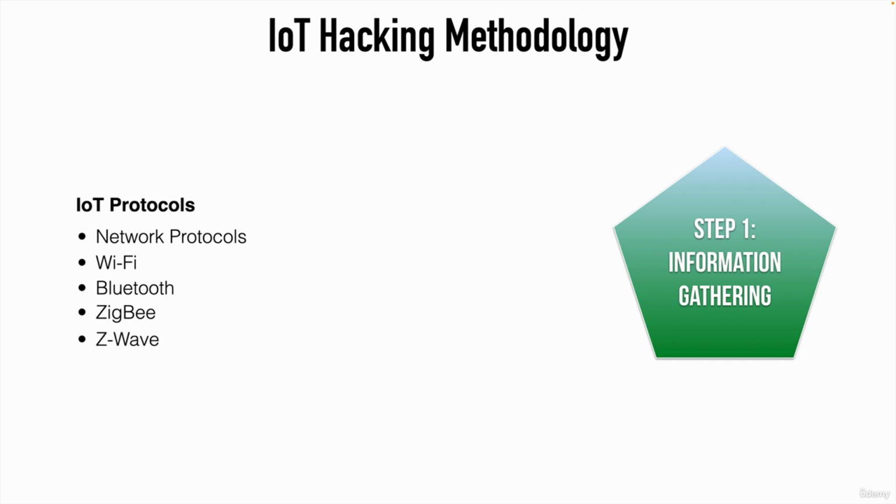This is also a low-power alternative to Wi-Fi, and it has a much larger range than Bluetooth. Z-Wave operates in a different wireless frequency as opposed to the previously mentioned Zigbee. So where Zigbee has to deal with potential congestion on the 2.4 gigahertz band, Z-Wave operates in the less crowded 800 to 900 megahertz range. For that reason, Z-Wave is considered to be more reliable in general, and we do see that a bit more.